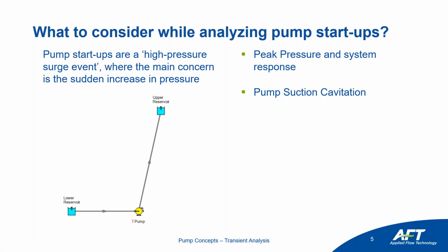is kind of total energy of the fluid at that point, some of that will be converted to kinetic energy, which means a decrease in static pressure. So if we, again, think about stagnation pressure in terms of dynamic pressure or energy in the form of flow, and static pressure, energy in the form of pressure, those things always have to balance. And so your static pressure can decrease suddenly when all of that energy is converted to kinetic energy, and it could drop so low that it could cavitate at that point.